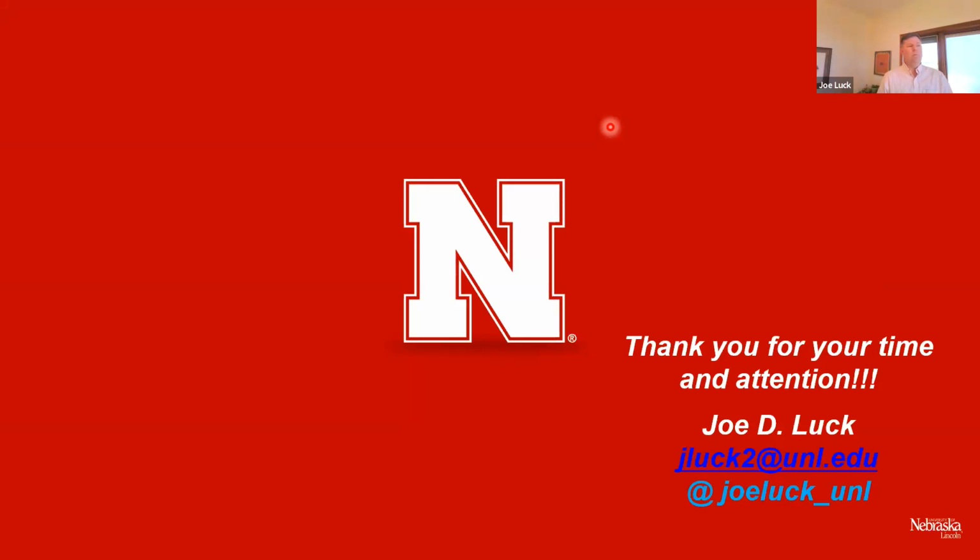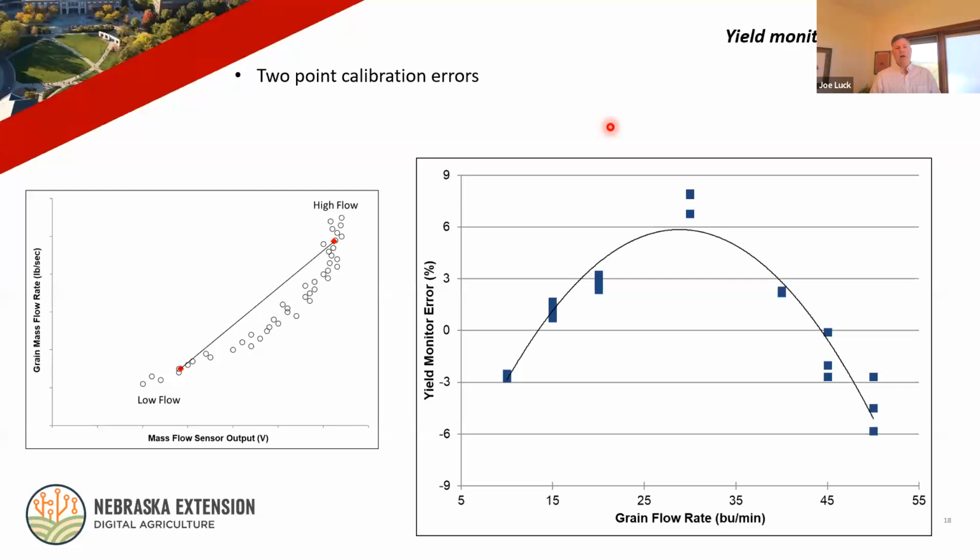And there's been a lot of companies in the past that have tried to use fewer calibration loads, which in some ways can be good. I think I can skip ahead here quick. This is some of the similar data that we pulled. You see that same kind of nonlinear output. With a 2-point calibration, you can actually start to see where I'm overestimating and underestimating. If you look at the error here, this is actual data from the facility.